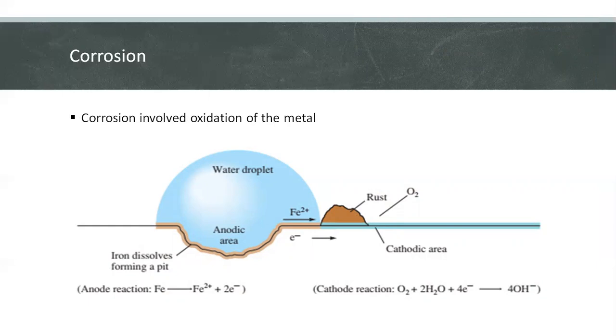The corrosion products of noble metals such as copper and silver are complex and affect the use of these metals as decorative materials. So under normal atmospheric conditions, copper forms an external layer of greenish copper carbonate called patina, while silver tarnish is silver sulfide, which is a thin layer that gives the silver surface a richer appearance.